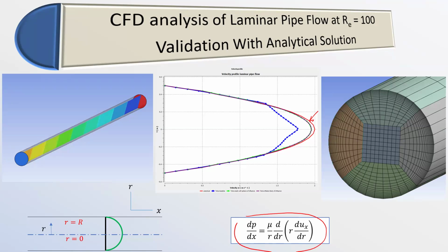On those discrete parts, we have the XYZ coordinates, and on those coordinates, we will solve our equations. So in CFD, what is happening is that we are converting the differential equations into algebraic equations, and then the software will solve them with the help of matrix methods. Like you learned in your undergrad maths, there are some methods that can solve the matrix, for example, Gauss elimination and Gauss-Seidel. But definitely in CFD software, the methods will not be very simple; they will be very advanced level. But I'm just giving you an idea of what is going to happen with those equations.